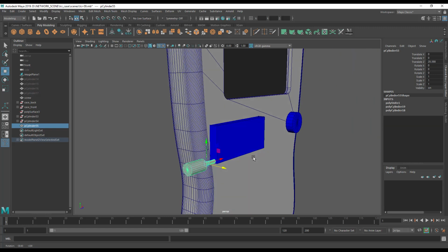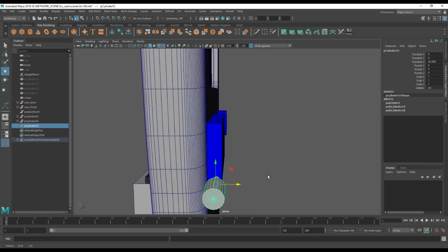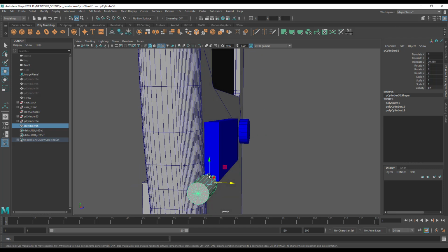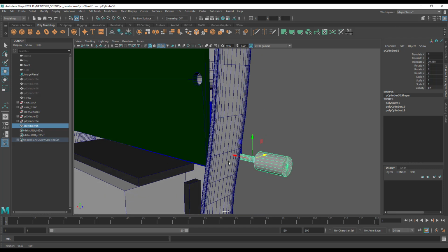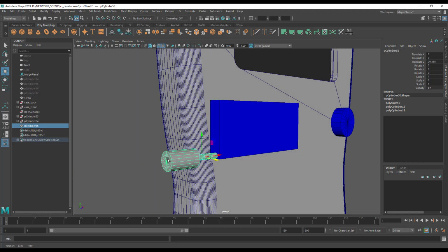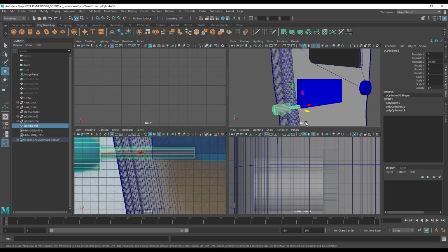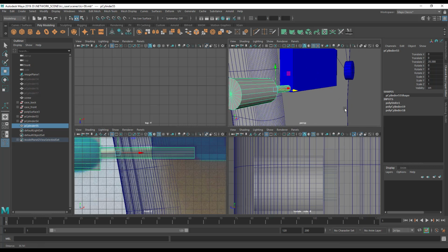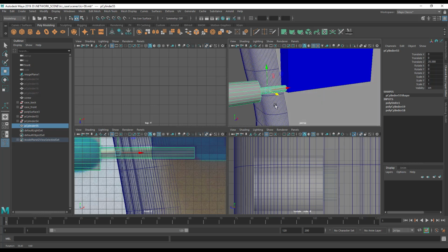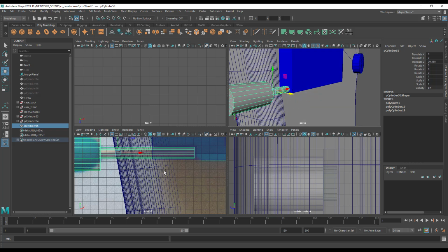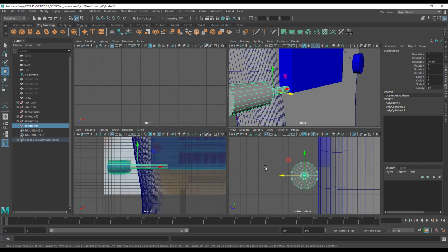So actually, is the ZIF socket clear enough that we do not need to cut a hole in the side of the case, because that would be very, very nice. Let me just check we're lined up on the picture. We are lined up in the picture. Right, excuse me folks, I'm just going to do a quick measurement as to how far down this bar goes into the ZIF socket. Okay, this bar actually goes 6mm down into the ZIF socket, so we need a way to do that.